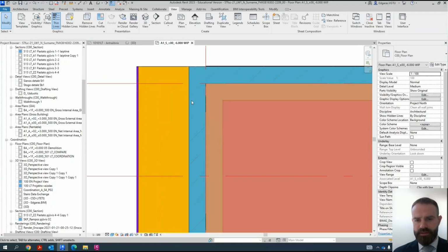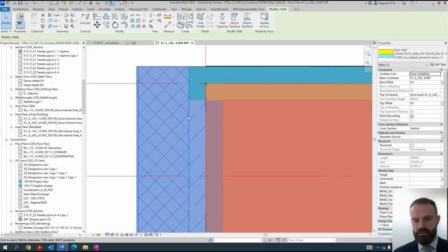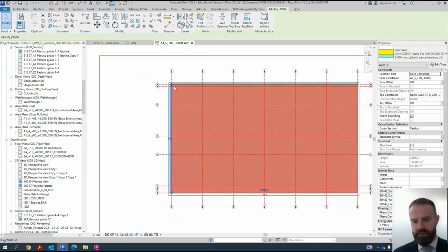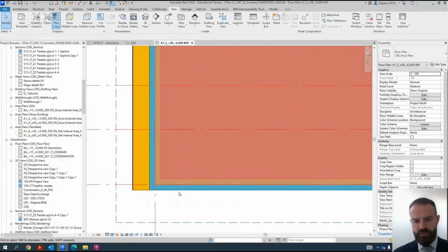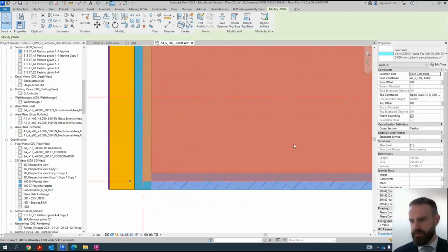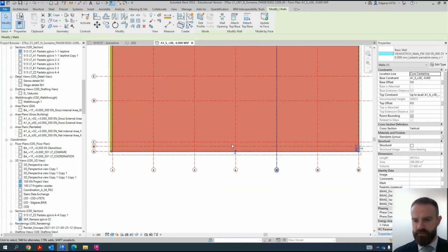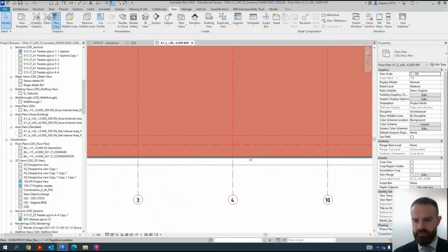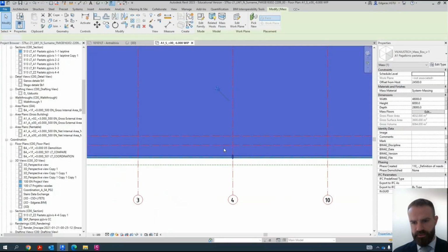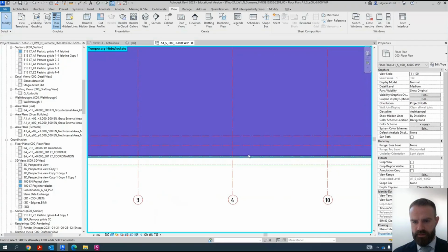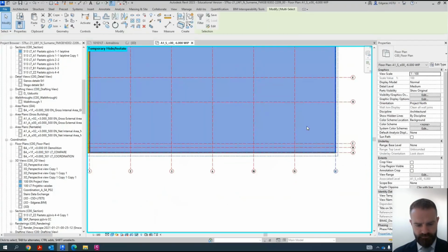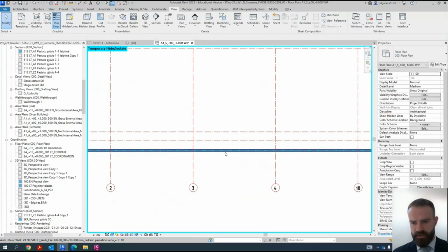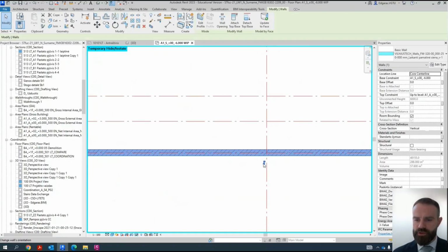If I select the wrong location line, all this part will go inside my building, and I can damage my project later. I need to fix it. So let's say if it's your facade wall, I will turn off this building part. Let's say my facade wall, my location of face of facade is not correct.